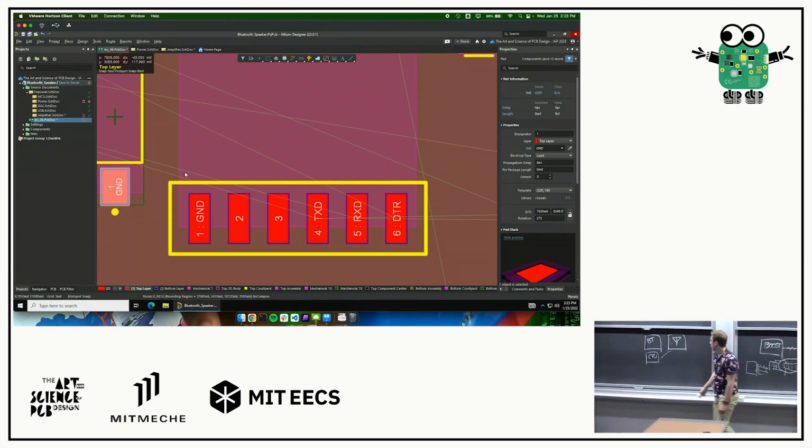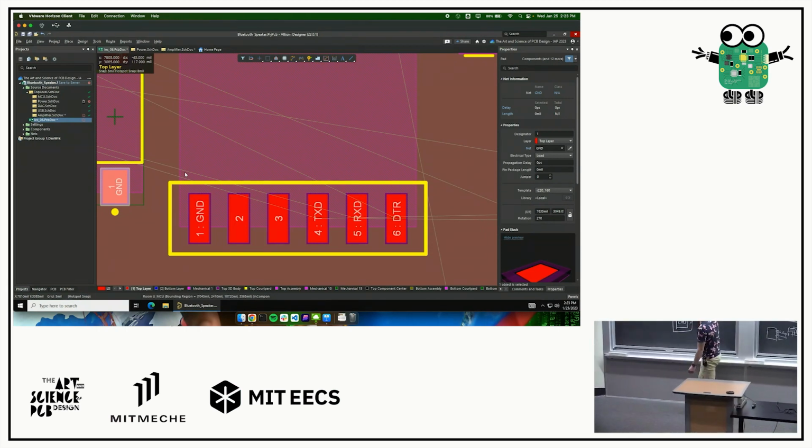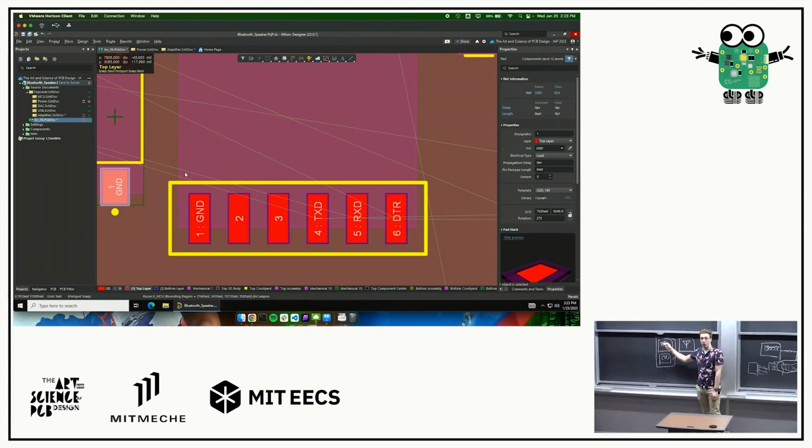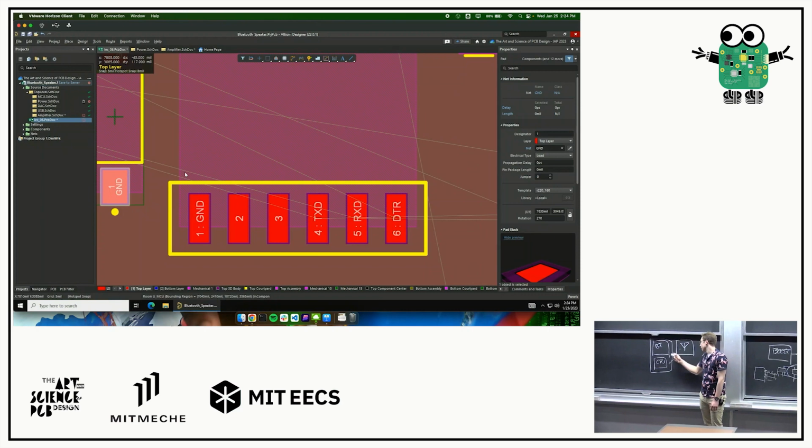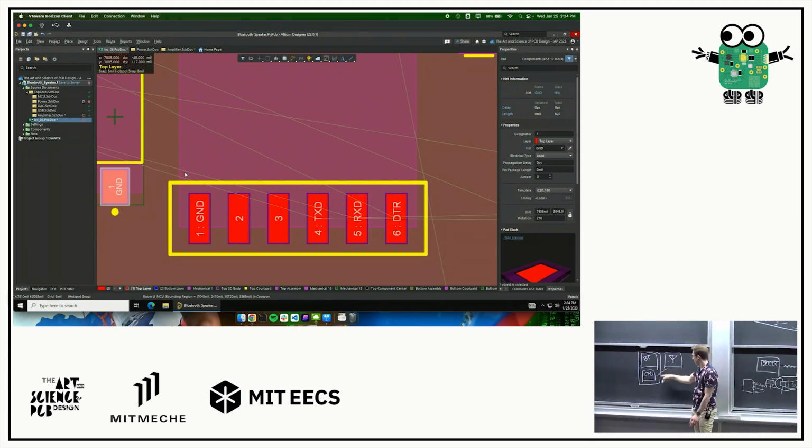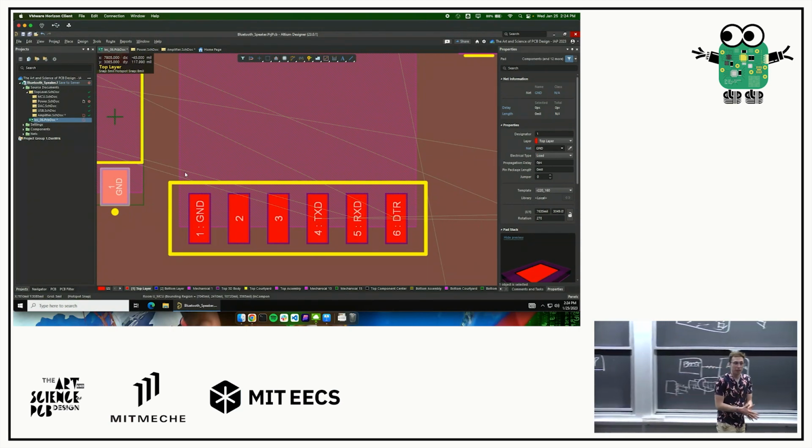What we could also do is just put a big metal shroud over this whole thing and drop a Faraday cage around it so that we have less noise propagating between the antenna and everything going on over here. So there's a case for separating the two, and there's other ways to mitigate that as well. Does that check out? Sweet.